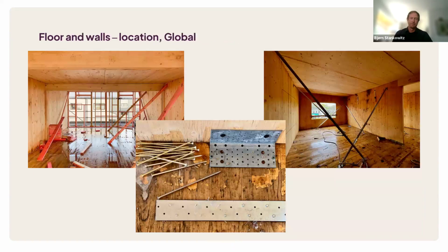saying that the gib ended up in the container outside of the window. So again, moisture in CLT buildings: we've got a floor above, and we've got obviously some penetrations, some openings, and the ends of the building are open. Driven rain can get inside, and no one is taking care of it. The floor just remains wet and moist, and leaving things on the floor attracts moisture, or attaching screws and then snapping them because we've got expansion in the timber.